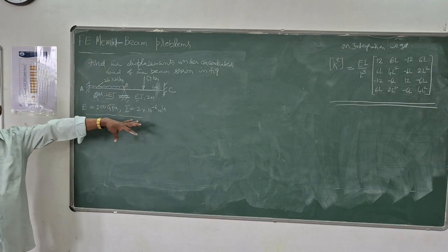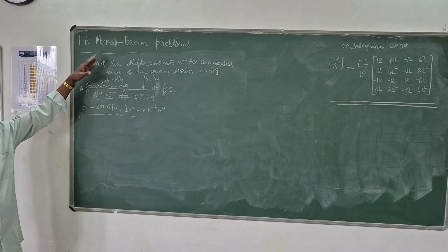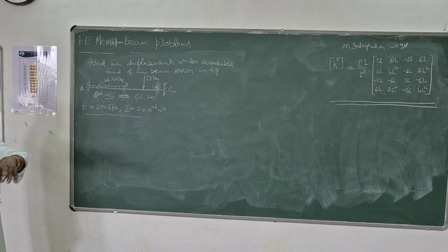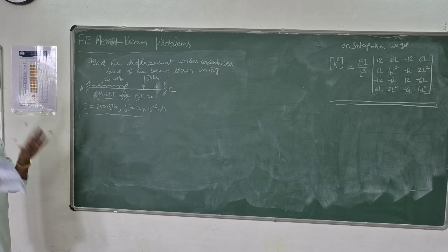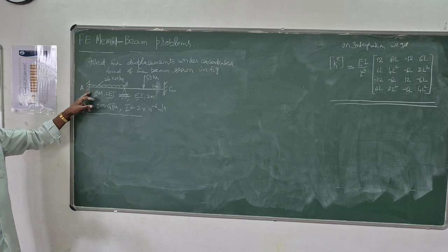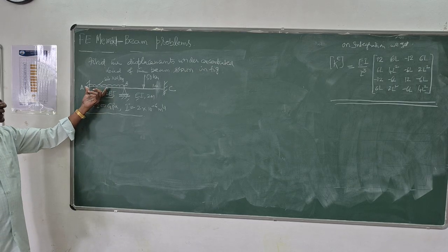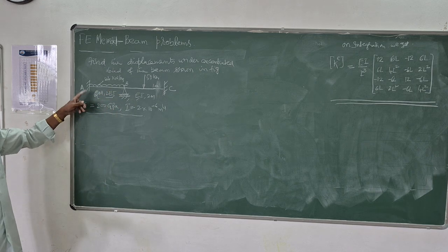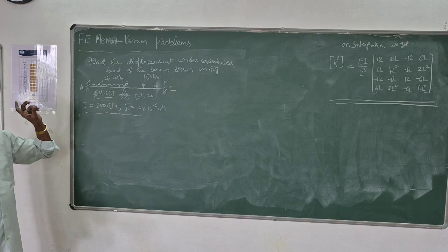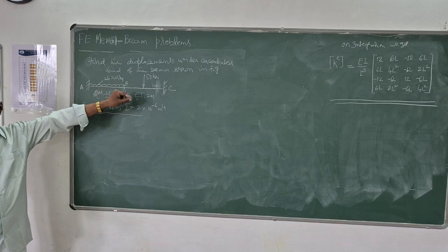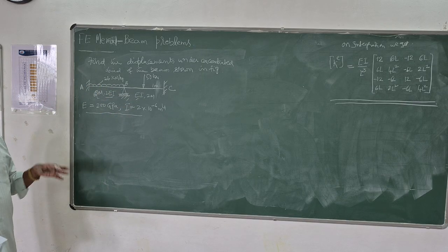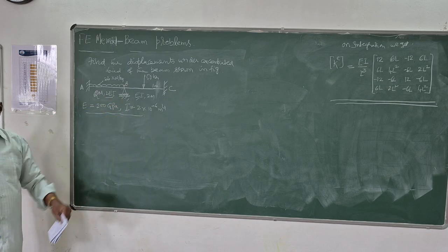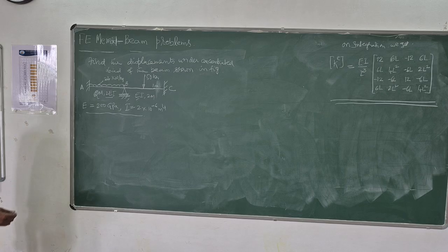So that we determine, and then using that moment and shear relationship, that's equation C and D, which already I have derived, that you have to remember, and they are all in natural coordinates. Each portion element you have to treat separately, and knowing the natural coordinate distance of any point where you have to determine the deflections, you can substitute that value and evaluate internal forces, moment and shear.